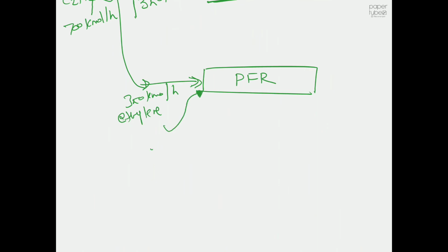It will be roughly 2 multiplied by 350 kilomoles per hour, and you can give this slightly in excess, say 1.08, slightly excess to the stoichiometric amount. So that should be 2 multiplied by 350 multiplied by 1.08 to maintain the stoichiometric ratio. Again ethylene will be the limiting reactant, and obviously you are going to get ethylene dichloride.